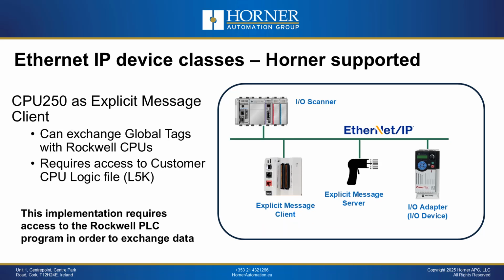Now let's talk about using the CPU250 as an explicit message client. This is a device that exchanges messages, typically tag data, with the I/O scanner, which is usually a Rockwell PLC.